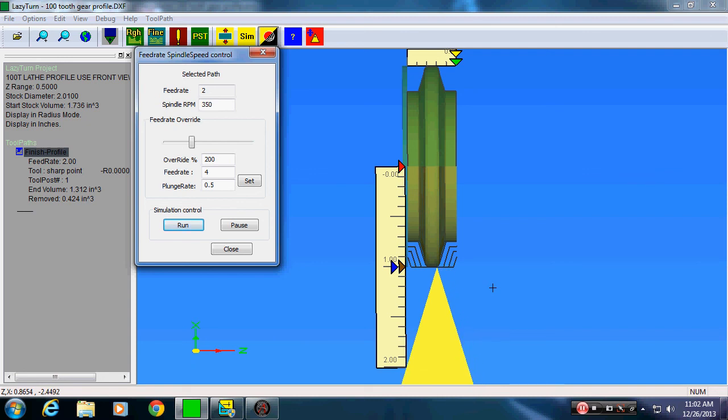but since it does work and it works pretty well, here's where I'd use the gauge that I made out of sheet metal on the mill, and I would just come in and work this by hand to take this last couple of thousandths off of here, and then hold my sheet metal gauge up to it until I finally have it right. And you could even do it with a really fine file, work it the rest of the way down with a little bit of sandpaper, a little care. I mean, you can get the shape perfect actually.